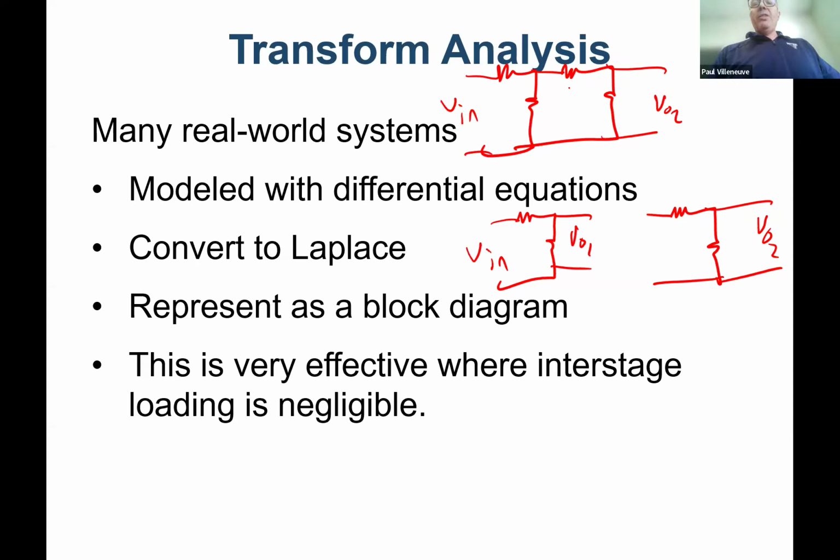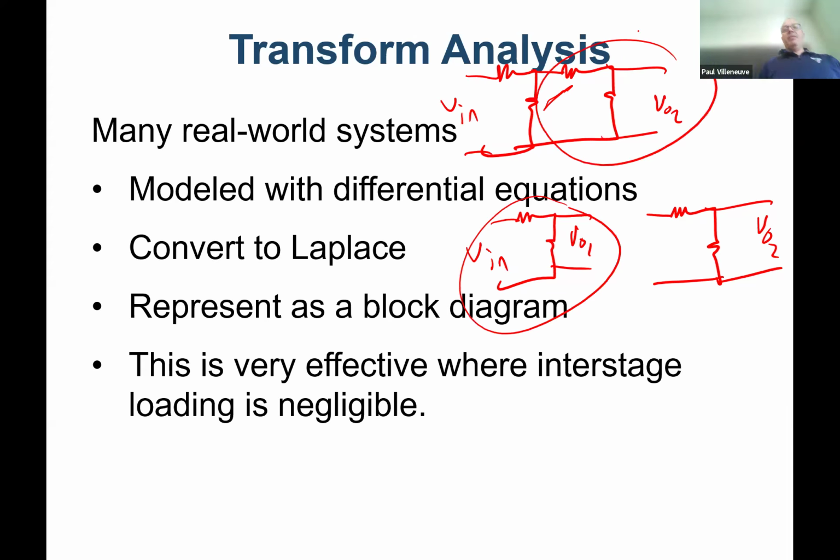But depending on these resistor sizes in here, I can get my results skewed, right? Because I know the voltage divider over here is not going to be 100% accurate because I've taken out that second stage. So what is the best way to go ahead and minimize interstage loading? I obviously can't physically separate them, right? Because I have to have some electrical connection between the two. So what devices can I use that don't really change my circuit all that much, but will result in negligible interstage loading?